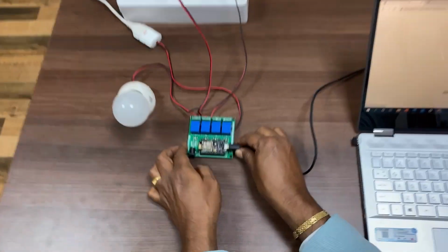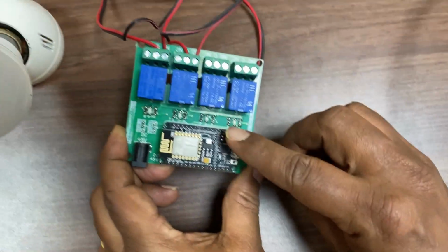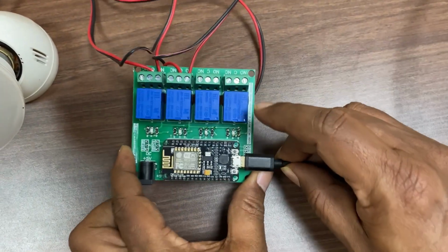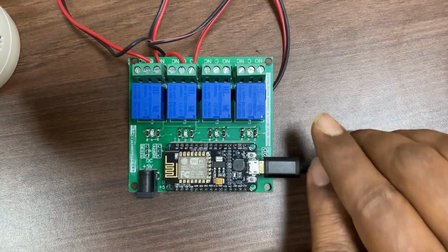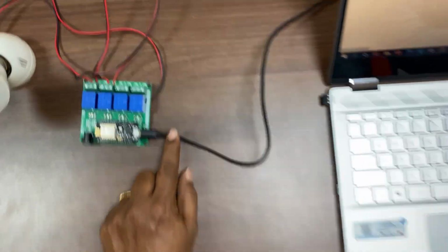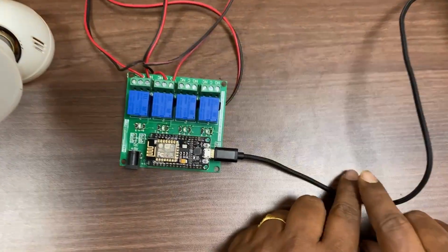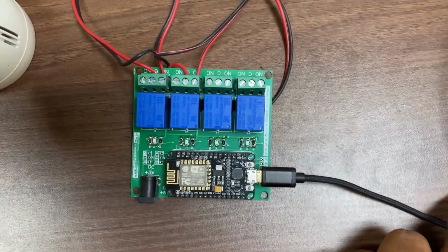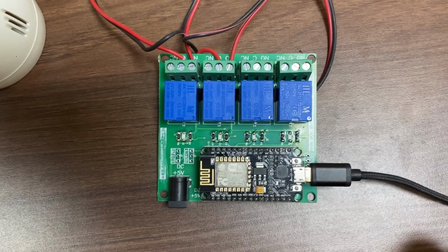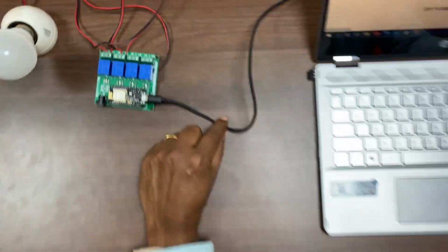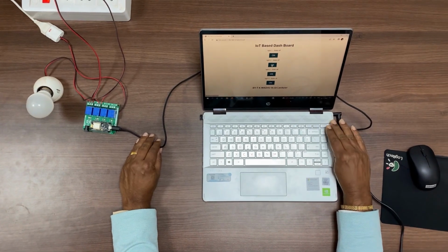Kindly note this board consists of NodeMCU, an optocoupler, driver circuit and relay. We should not use a direct interface to the laptop. We have to use optocouplers. So if there is any short circuit, or if students make any mistake, the high voltage will not be fed back to your laptop USB port. If you don't use optocouplers, there is a chance of damaging your laptop.